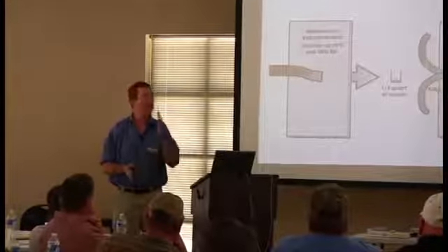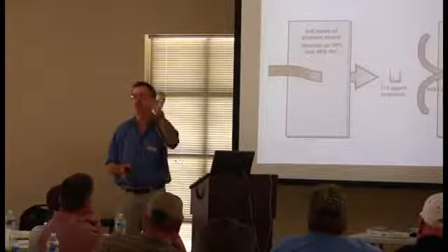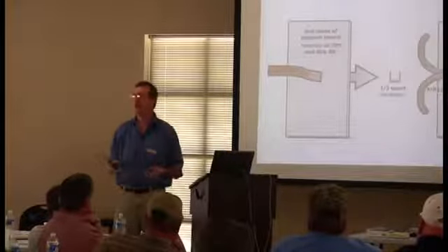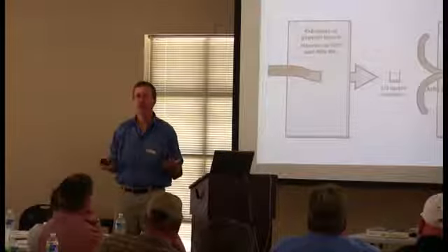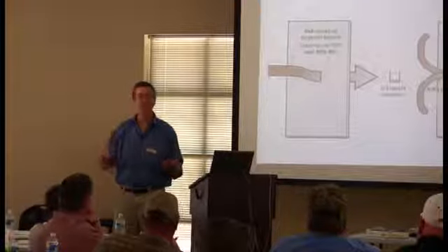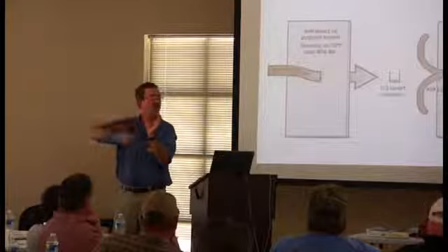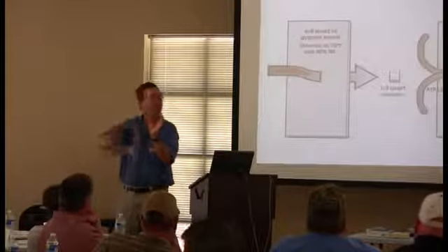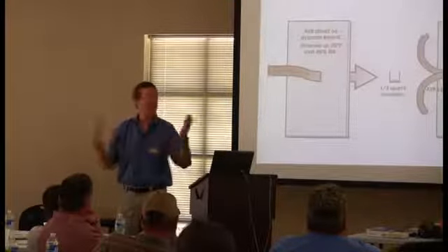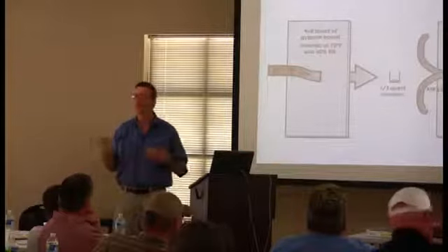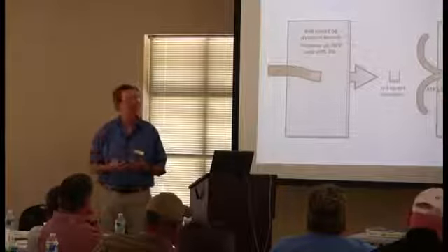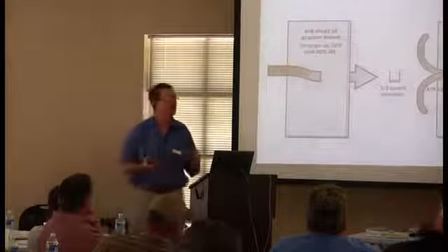We should have treated synthetic stucco just like a brick veneer wall. How come a brick veneer wall absorbs all kinds of moisture, right? Brick cladding absorbs lots of moisture. How come the wood wall doesn't rot? What's between the brick cladding and the wood wall? An airspace and a water shedding surface, right? So if we had done the exact same thing with EIFS, synthetic stucco, that would have worked fine. But when we didn't, that was the problem.